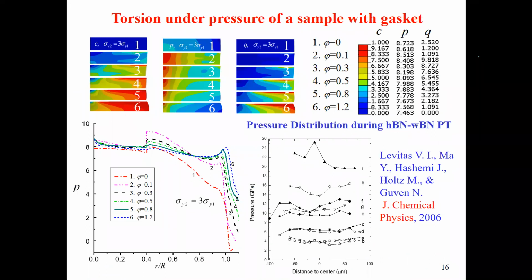And what is the advantage of the rotational diamond anvil cell, despite the fact that the physics is the same? We can control the loading path. After some optimization for the same problem, I mean geometry and gasket, we obtain a result where, during quite significant shear and during phase transformation, pressure does not grow. So we can keep pressure constant and run the phase transition by increasing plastic deformation.